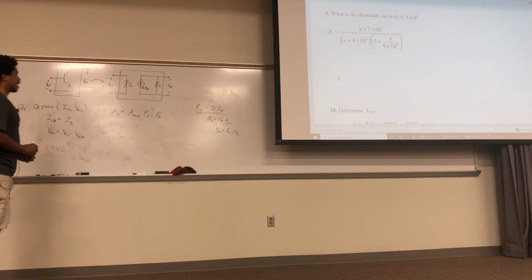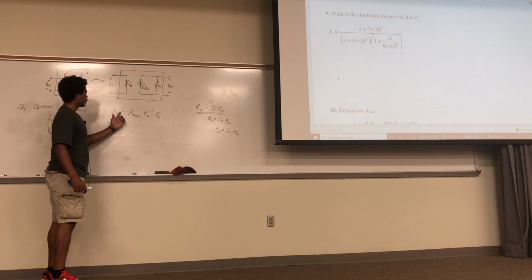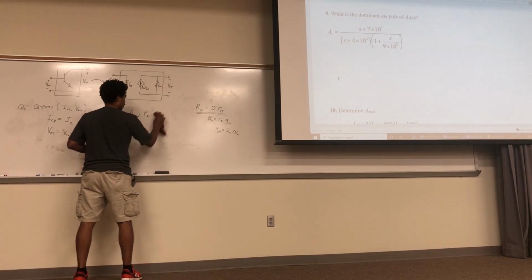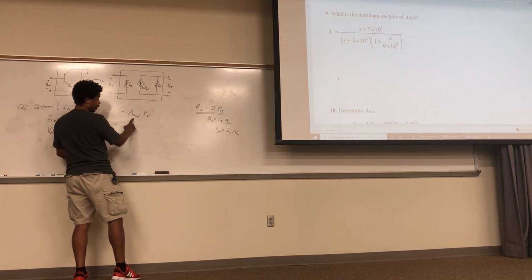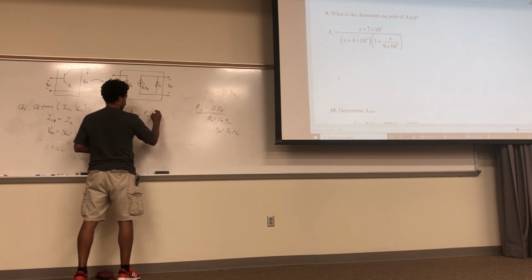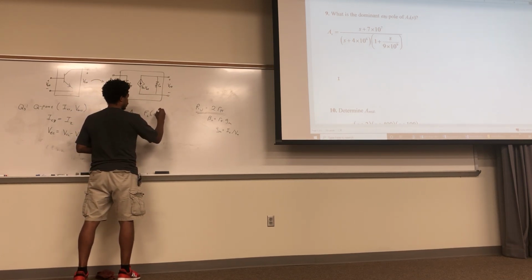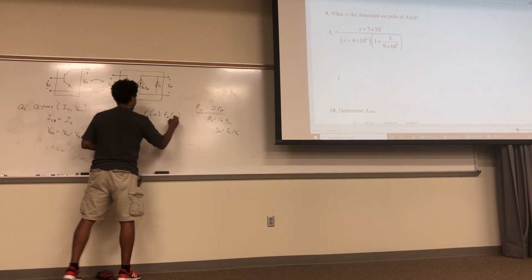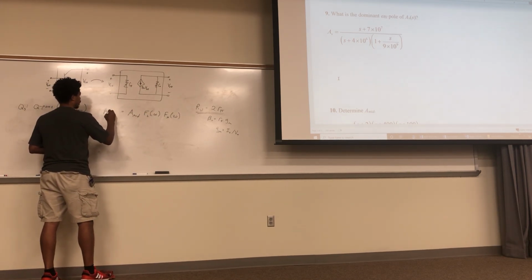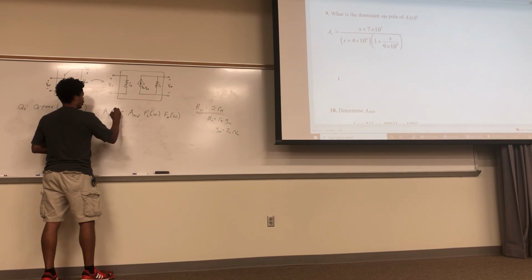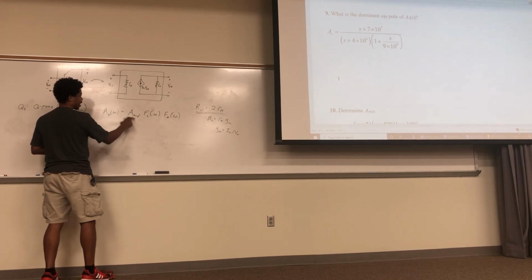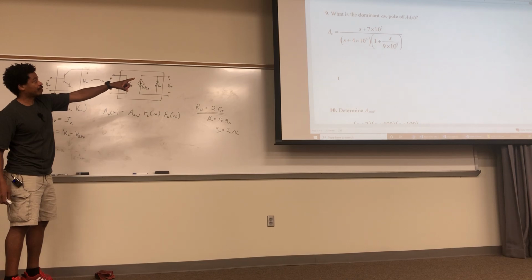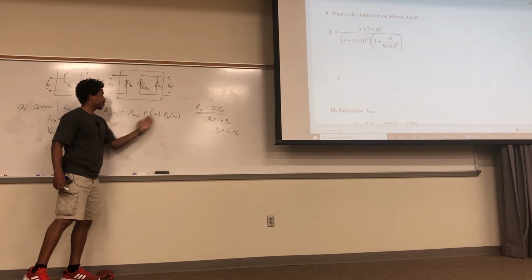And the thing was that, let me scoot this over a little bit. So that's a constant. Okay, this is a constant. This right here is a function of frequency. This right here is a function of frequency. And so this right here is a function of frequency. And this is what you would do your Bode plot with. But that is a constant. So you can take any of these transfer functions and break it up into these factors.